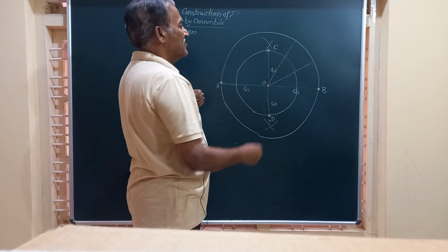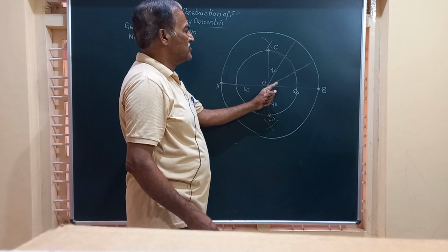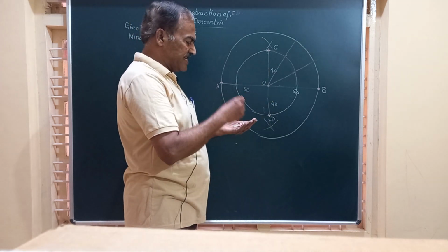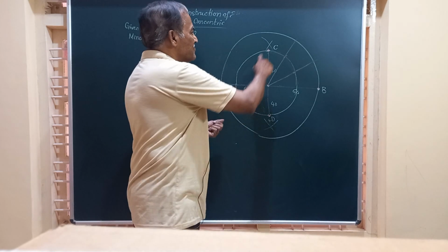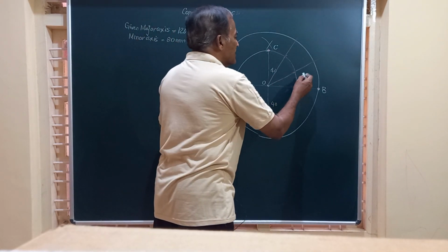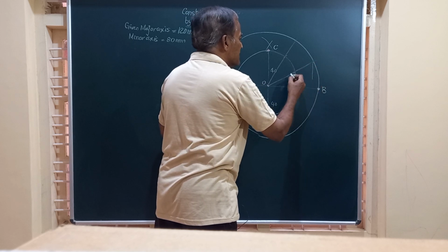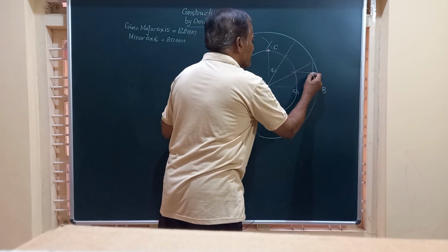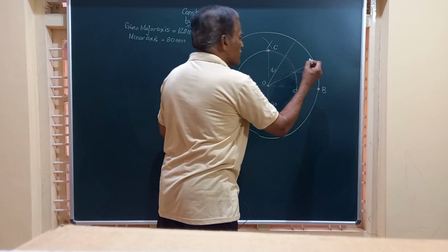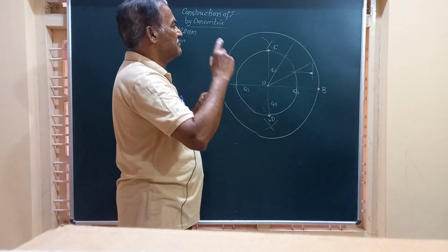So we have got the quadrant 90 degree divided into 3 equal parts. So let us complete the ellipse for this part, friends. It is very simple. See, draw a vertical line from the major axis, a horizontal line from here.